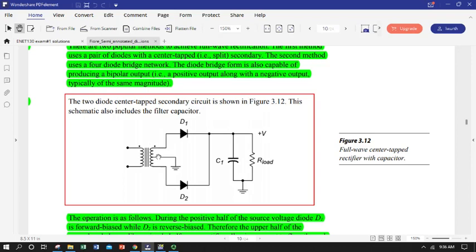And because we can only have the full secondary voltage over the full coil, what we'll be doing is splitting that and centering it. So if, for instance, our secondary peak voltage was supposed to be 12 volts, so that's amplitude, one peak was 12 volts, we would have 0 here in the middle, and we'd have +6 and -6. So a total of 12 over the whole coil, and split evenly in the middle, because ground is always our 0 voltage reference.